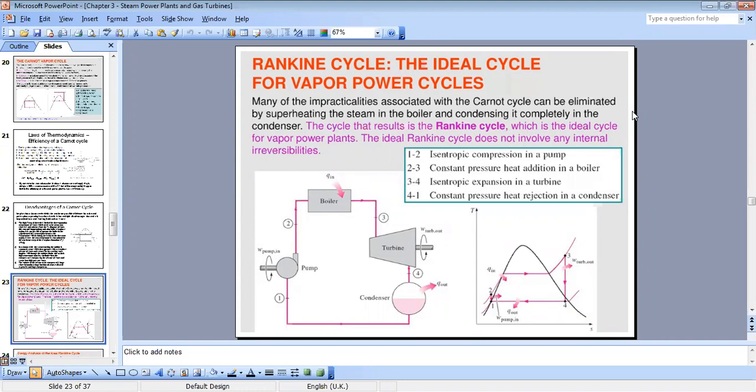for the compressor, we can have gas, a mixture of gas and liquid, and we said that for the pump or the compressor, it's better to compress a liquid. And also for the turbine, it's not advised to have droplets of liquid because it will cause erosion of the blades and it will deteriorate them. Okay, so we need to come up with new solutions.